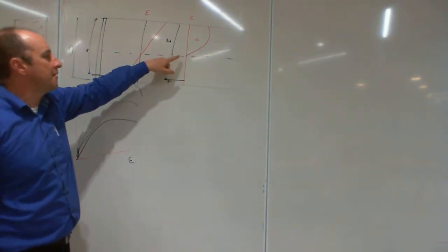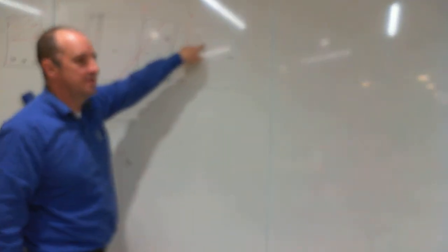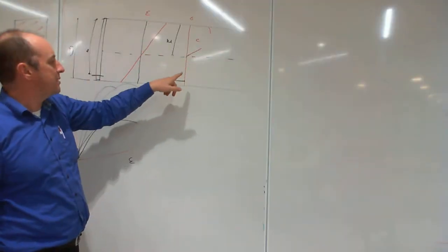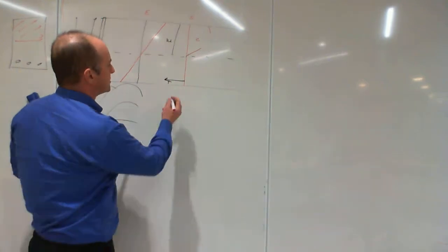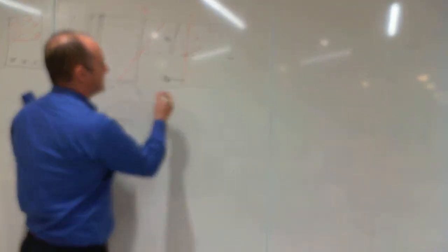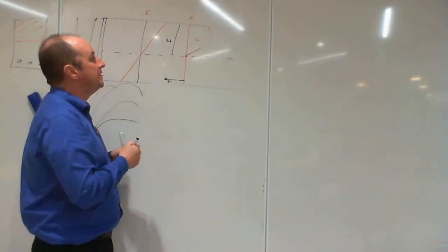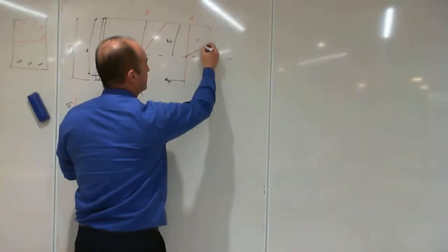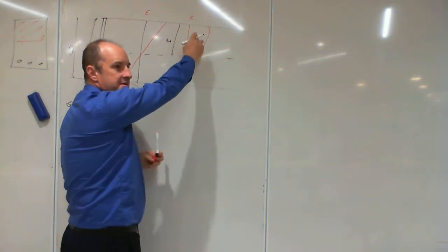Okay? Now, the thing about analyzing that shape, to work out the bending capacity of the beam, we've got to take the moments of that force around the neutral axis. So here it's pretty easy. It's force times that lever arm. Here you've got to integrate that curve, find the centroid, take that. That's a real pain in the rear, so we don't do it.